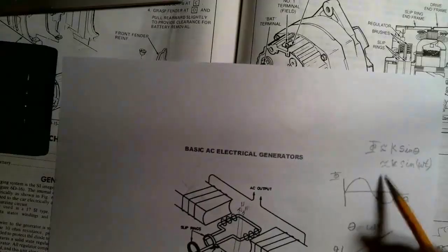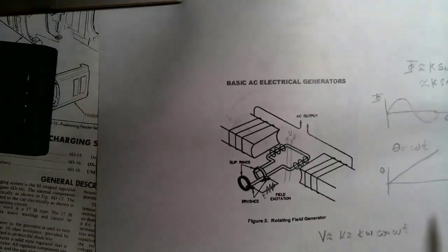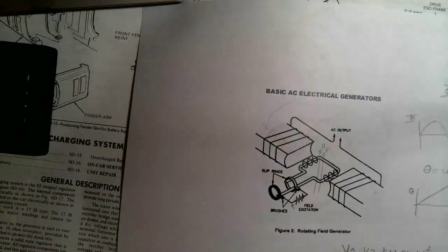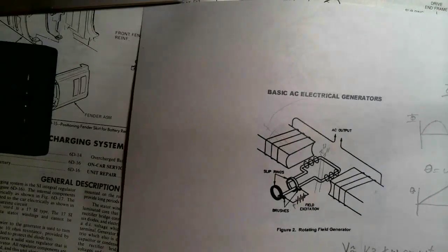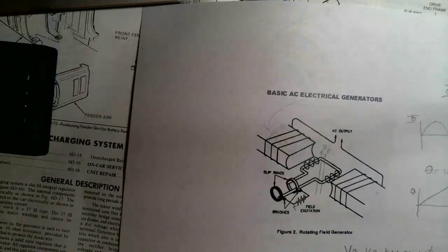Again, here's our flux, K, some constant times sine omega t. Our voltage is some other constant times K omega cosine omega t, because the derivative of sine is a cosine. So, obviously, one of the constants that we have to deal with here is if we have a voltage per turn, well, we got 6 turns shown here. Well, we obviously have 6 times as much voltage as what we have per loop, because we got 6 loops